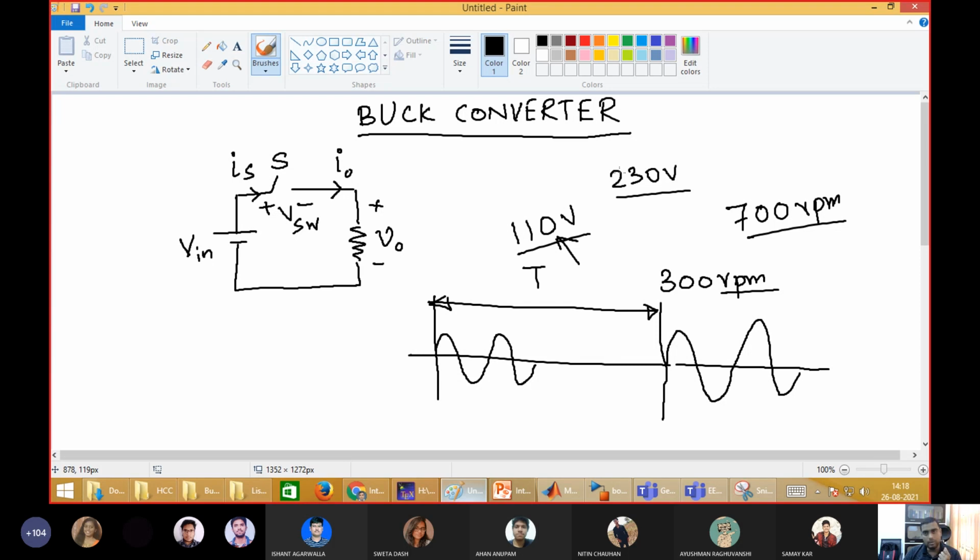Now let me ask you: suppose the inertia of the fan is very low. Will this method work? No, sir. Why? It will go to high speed instantaneously. Changing the voltage won't affect it much, because once you switch it on, it will immediately go to high speed, and when you switch it off, it will immediately stop. Very good, that is the reason.